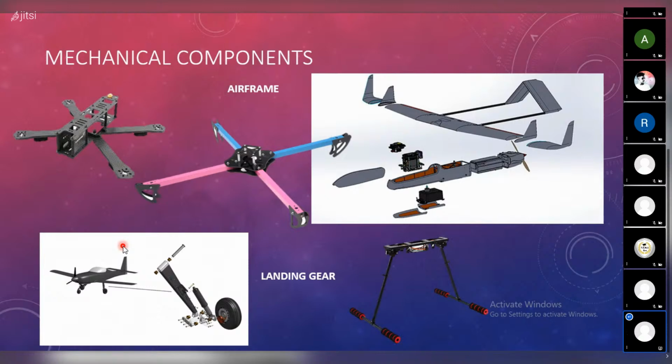You can use various materials for the same, but definitely, if you remember from our previous discussion, it has to be lightweight. So mostly nowadays carbon fiber, aluminium, glass fiber or composite materials are used. If you know the characteristics of carbon fiber, they are lightweight but stronger than steel. So it's very apt for such an application in drones, as you want to keep the drone very light, but you need it to be strong enough so that you do not lose your drone just because of one crash. So carbon fiber is generally used. Then we have aluminium, and other composite materials like glass fiber, etc.